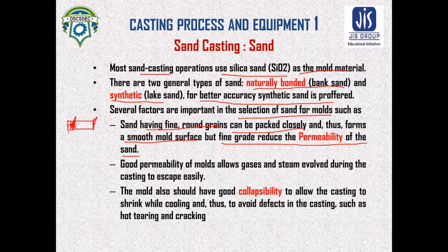And now if in the mold some gas is formed by any reaction, that gas cannot move. That gas can get trapped in the casting. This is a problem, and it causes defects in casting.